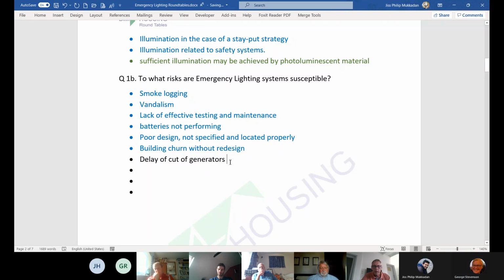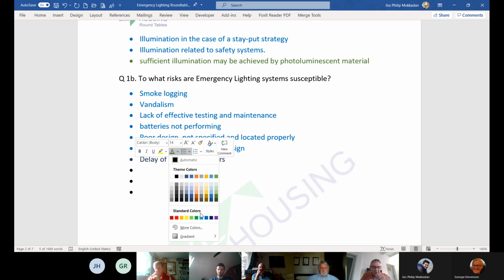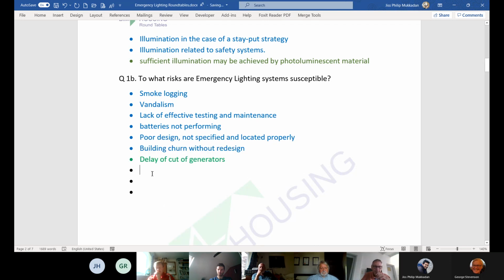The other one, if you're going to talk about historical systems, you had to hit exactly the right point in the main cycle for high pressure lamps. Otherwise, they would extinguish. That was my restrike point. Yeah, restrike of some mains luminaires.